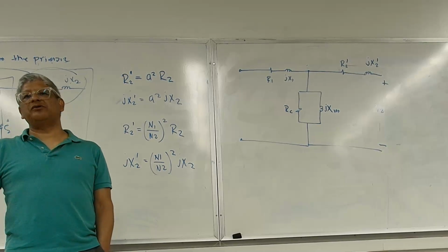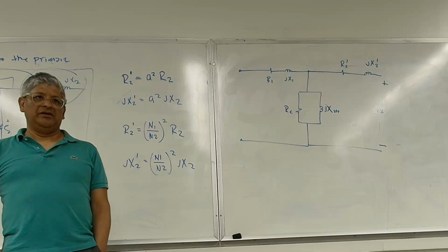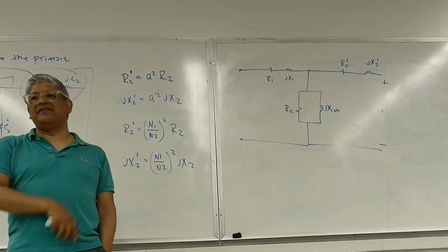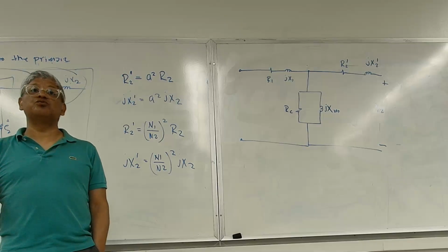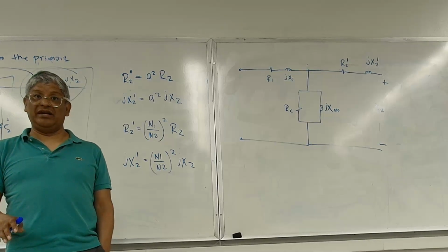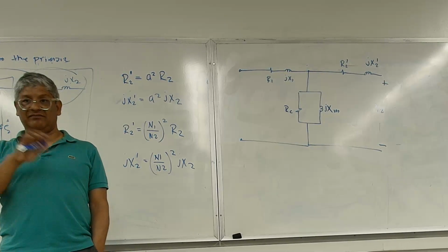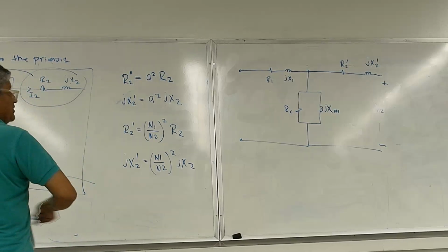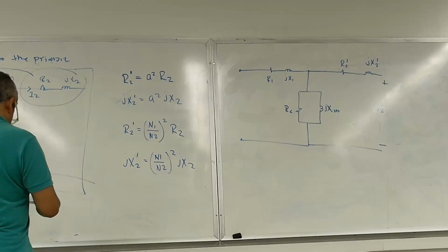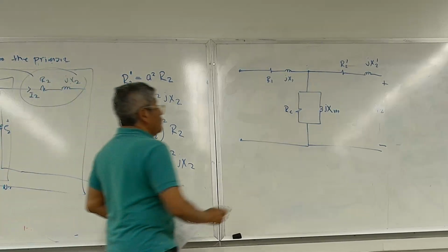But if you go to a power station, it's the other way around. The source is on the low side and the load is on the high side. So primary only means where the source is connected, okay? It doesn't mean high, although high, of course, means high voltage, low means low voltage, but that's how we define primary and secondary.